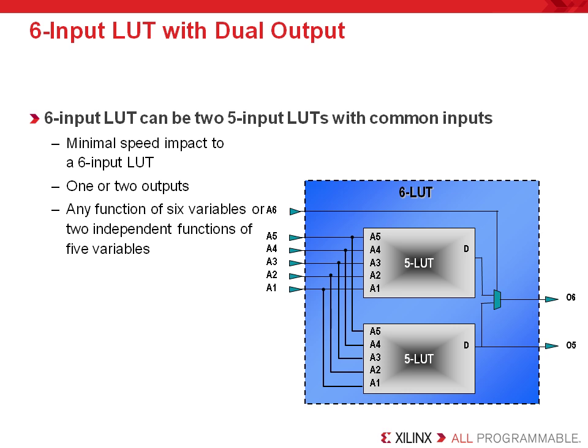This slide highlights the fact every 6-input LUT can be programmed as 2 5-input LUTs with a separate output. We added additional registers because the LUTs can be broken into 2 5-input LUTs, and this should help designers get more logic out of their FPGA design.